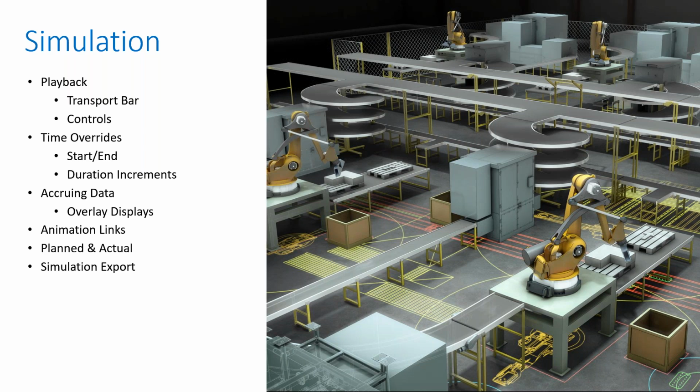And then one other question came in from Felix. Is there interoperability between Navisworks and 3ds Max for better visualizations? So Navisworks will open FBX files coming from 3ds Max, but there's no plugin that directly switches back to 3ds Max like you would have for Revit or for AutoCAD.